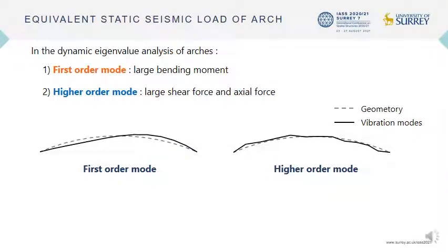Next, I would like to talk about the equivalent static seismic load. There are two dominant vibration modes in arch structure. One is the first order mode with large bending moment, and the other is the higher order mode with large axial and base shear forces. Therefore, we use approximate vibration mode based on the continuum theory of arches.